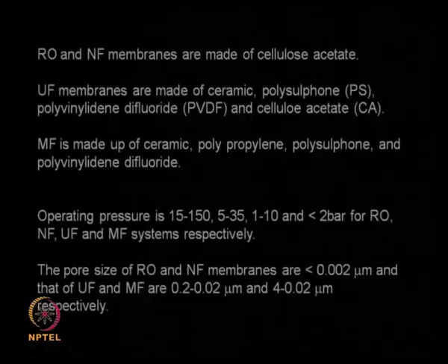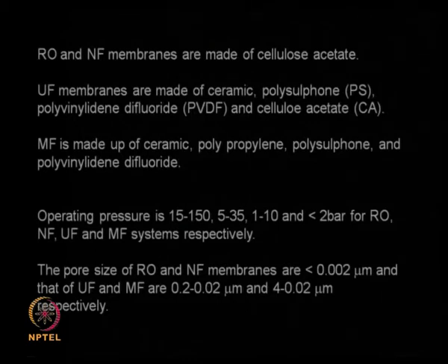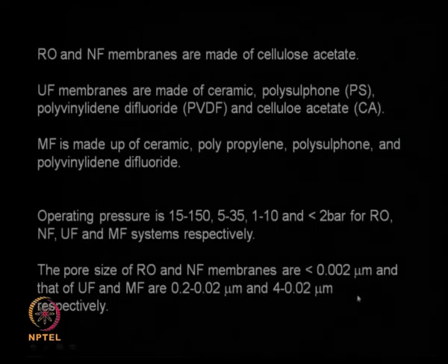So sometimes if you want to do an RO type of job, you may have an ultrafiltration before it to capture as much dissolved solids and suspended solids, then you may go to an RO type of membrane. The pore size of RO is very small, practically no pore size at all, ultrafiltration pore sizes are much larger, and microfiltration pore sizes are larger still.